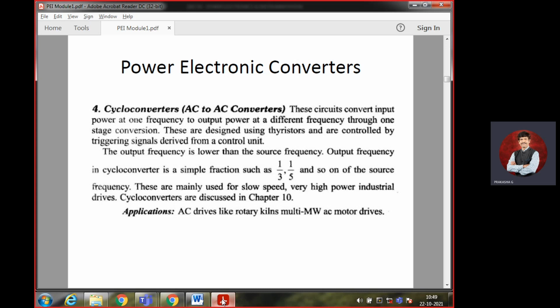Now what I will do, I'll put the regulator to 0.2. When you put the regulator to 0.2, instead of 10 kilo ohm, it's going to reduce to 5 kilo ohm. Means resistance is reduced still further. Since the resistance is reduced, the current flow increases. It's inversely proportional. Correct? As the resistance increases, current flow decreases. As the resistance decreases, current flow increases. So when I put it at the final stage, maybe I may have around 500 ohm. Just assume.